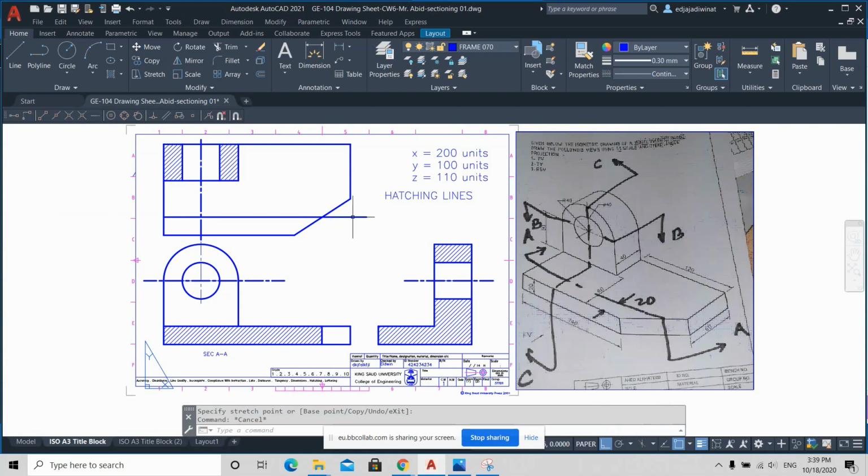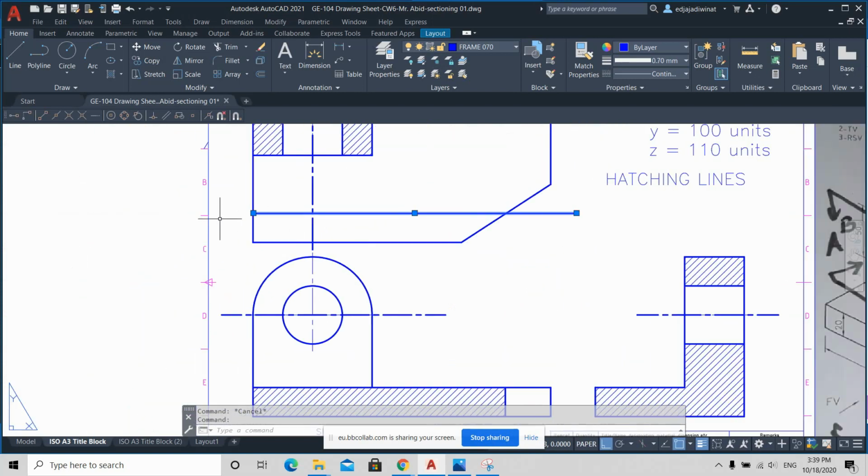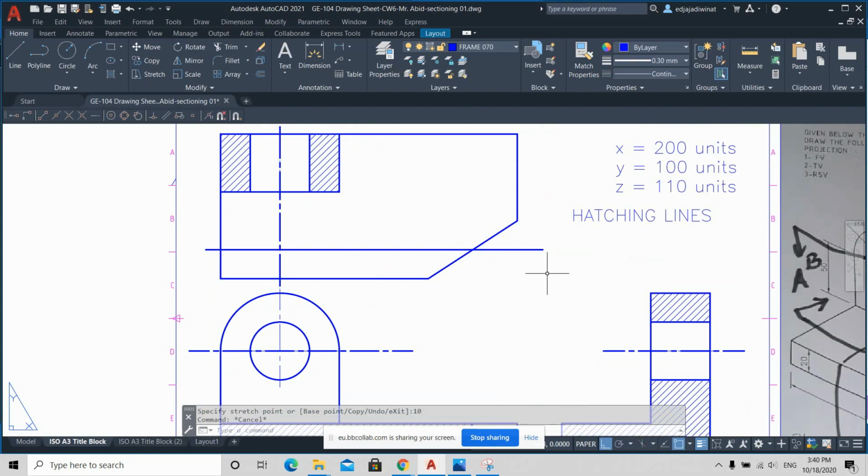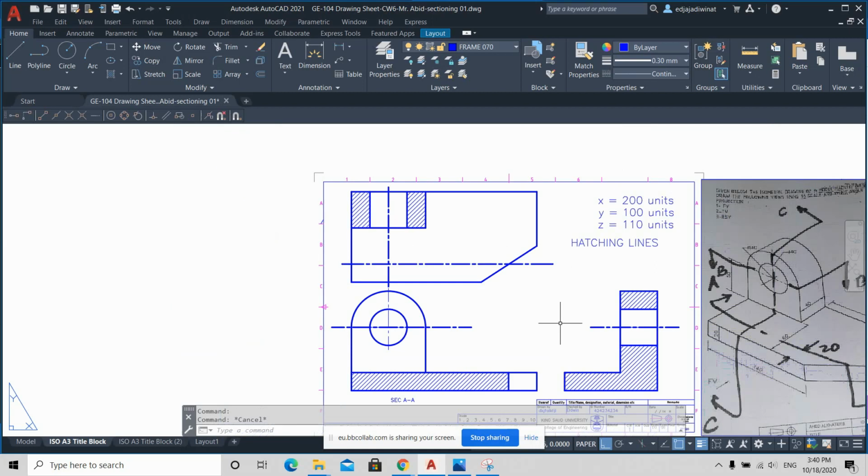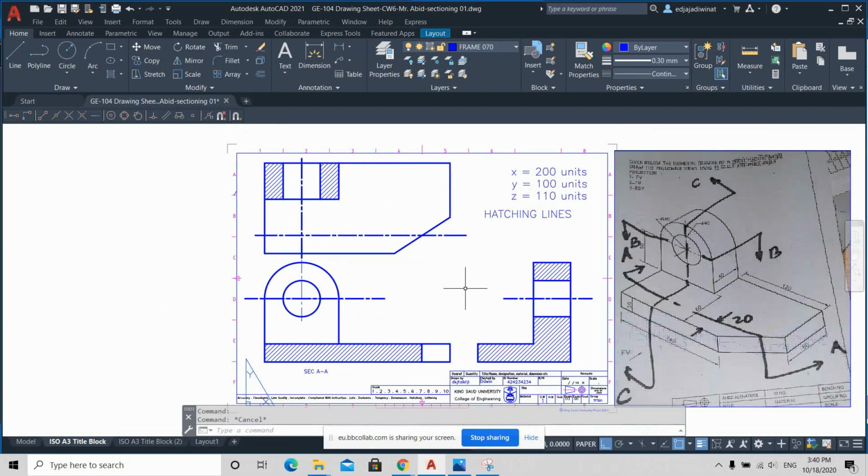And this one, you just extend also out of the object. Say I'll extend 10 in this case. Again, there's no fixed value. Now this is just a normal line, and then you change it to center, and the line weight should be 0.7 there.